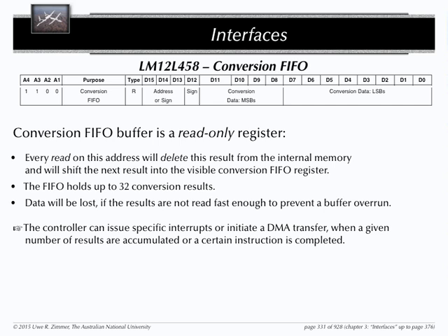You trigger a specific event on an I/O line or on an I/O interface. You then also trigger a DMA transfer so that the data is automatically stored somewhere else in memory where you can, in all calmness, access it later on. You can, for example, unroll this built-in FIFO buffer, which you can only access the oldest value from. You can just tell a DMA controller, read from this thing 16 times, and roll it over in this memory block and write these words which you read from there in there, and then leave me alone. I can look at the CPU later on in this area, what are my 16 latest values, and can do something else.